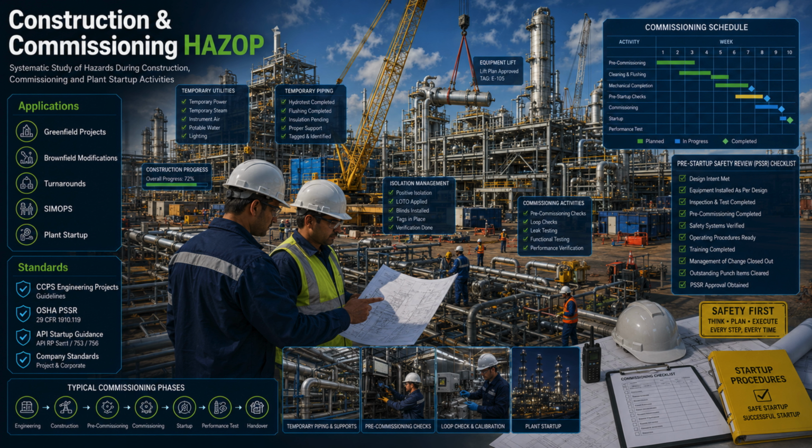The construction and startup phases introduce many temporary risks. Construction and commissioning HAZOP focuses on hazards during construction, pre-commissioning, commissioning, startup, plant modifications, and simultaneous operations. These studies are supported by CCPS engineering project guidance, OSHA process safety management requirements, API startup guidance, and company commissioning procedures.